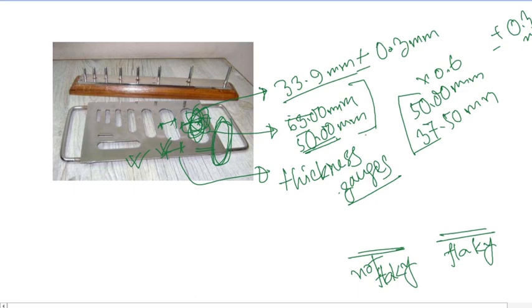Whenever you test the particles passing through 50 and retaining on 37.5 millimeter, you will try to pass all those particles through this opening, rotating them through 360 degrees in all possible ways. If a particle passes through that opening, you treat it as flaky and keep it combined with the previous ones.